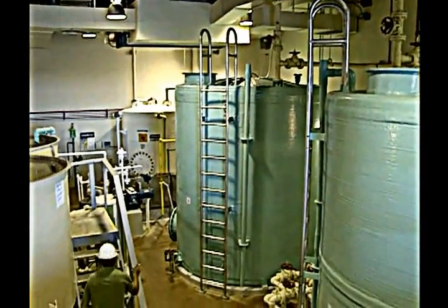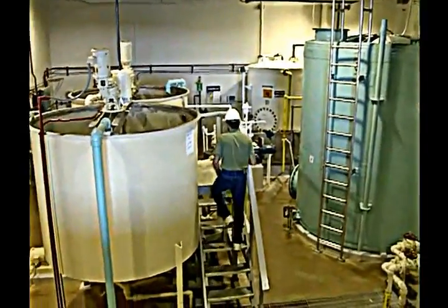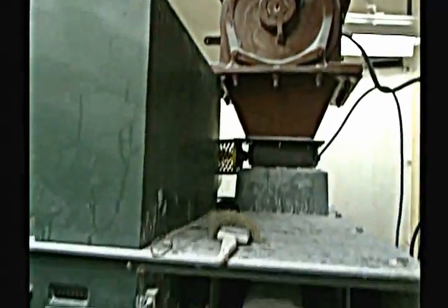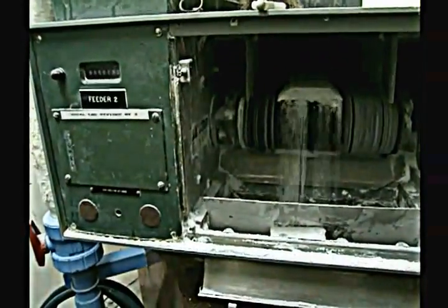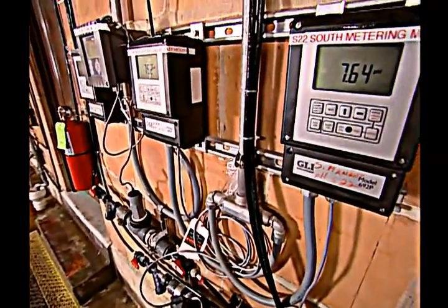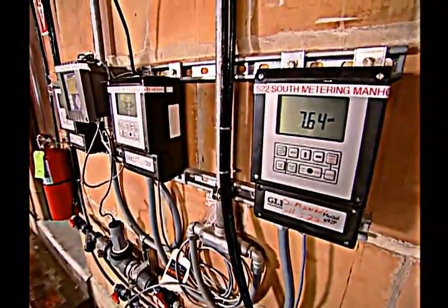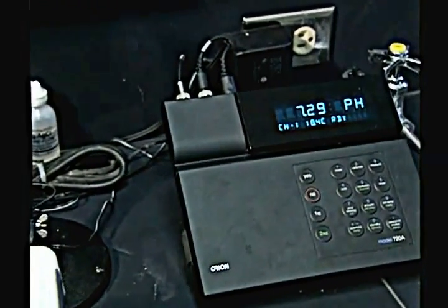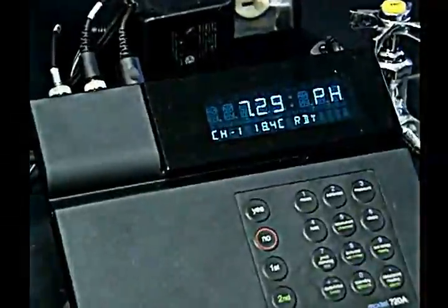Chemicals are also used prior to coagulation to help the water respond better to coagulant chemicals. Lime, soda ash, caustic soda, and sodium bicarbonate are used to increase the alkalinity and adjust the pH of water. If the alkalinity is too low or pH values are out of range, later changes in alkalinity or pH in treatment or the distribution system may cause floc to reform, causing customer complaints or a buildup of sediment in the distribution system.